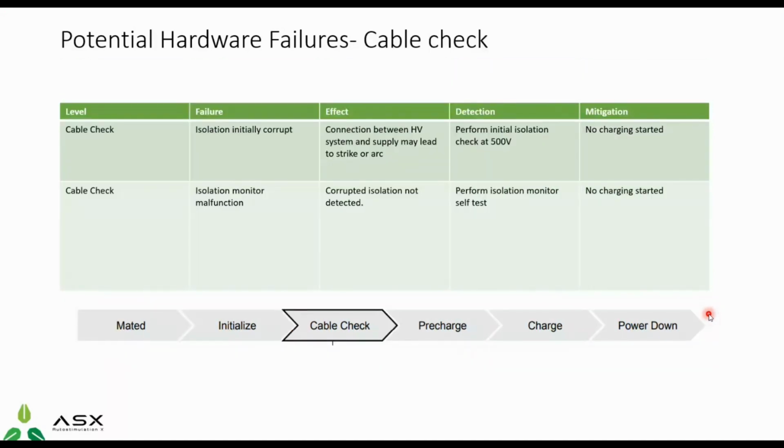So the physical check again, we have the cable check. We are finding isolation monitoring malfunction and all that stuff. For checking that isolation monitoring, we have an isolation monitor in our EV emulators, and it also gives us information on why isolation is not up to the mark, maybe the cable fault or maybe the connector fault.